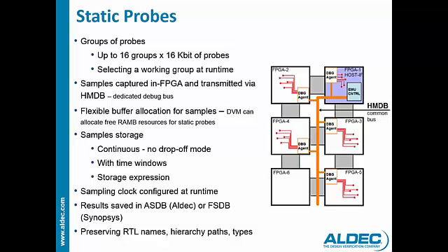If you've got multiple clocks in the design, then it is possible to choose which clock to use as the sample clock, and you can do that at runtime, and that obviously will influence how fast the emulation runs. All the results are saved in simulator-friendly formats, with RTL names and hierarchical paths being preserved.